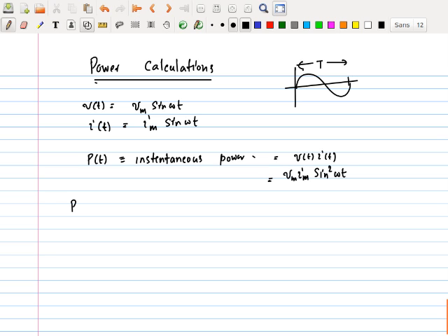So, in your advanced level, I don't know whether you did it, but to find the average power, what we do is we take our signal through a single cycle of P(t). This is what this means. For a single cycle, I am finding the area under the graph, just adding up everything. Then this is the interval of time. If I want to write it like this, it's fine. Over T is going to be the average power.